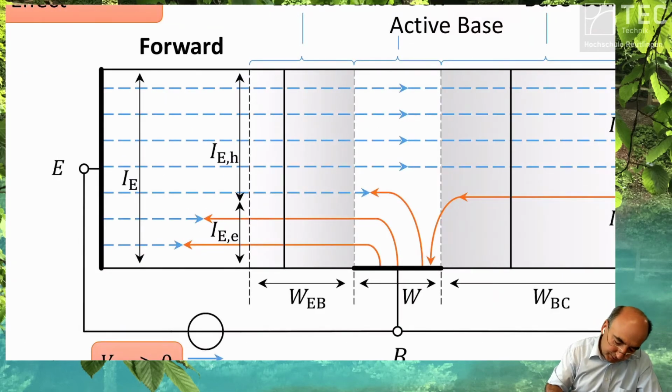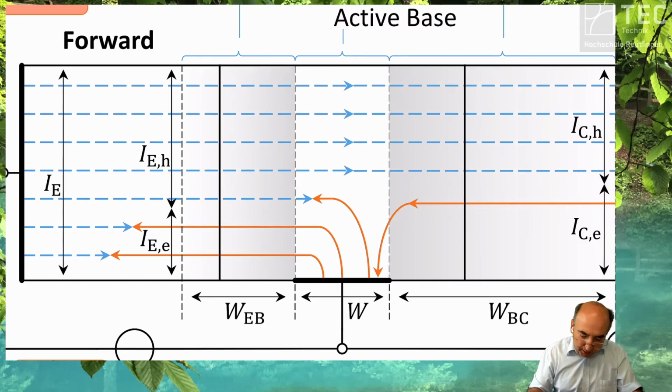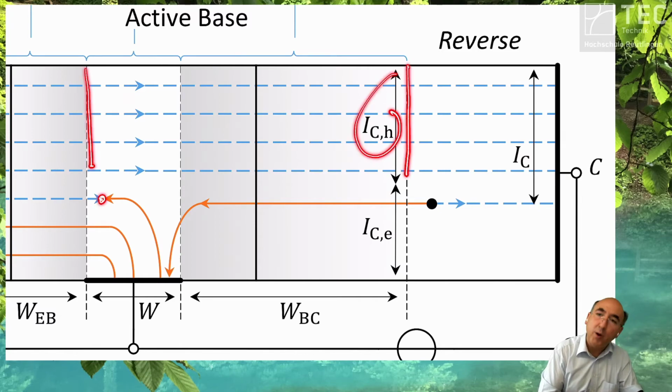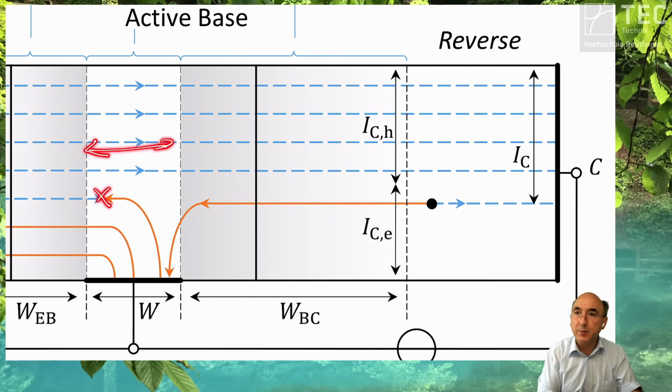Okay, now we are here. So we have this portion and this portion. Let's go on. We assume that here we have the same as at the PN diode. Now, let's go to this boundary. And at this boundary, we have a slightly different hole current here compared to here because of this recombination. But we assume that this width is so small that this change is negligible.